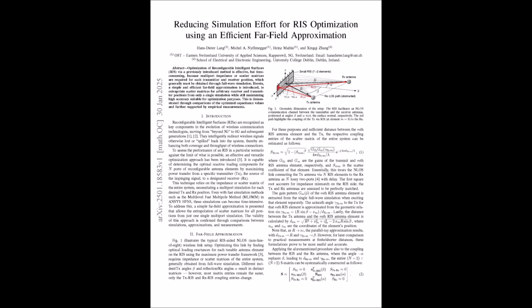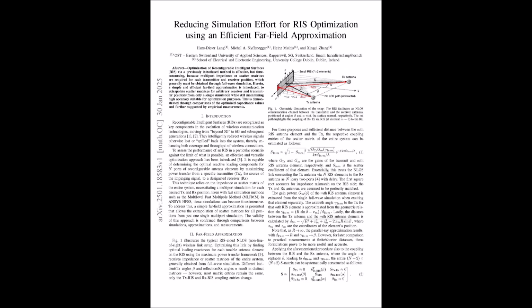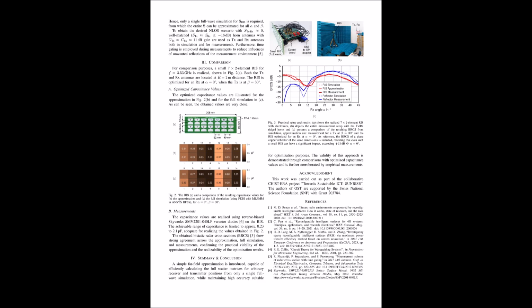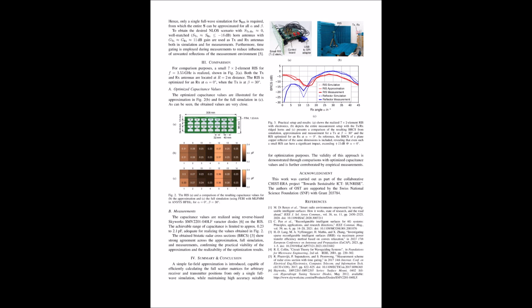All right, so we've got this big matrix filled with smaller matrices. Can you unpack those submatrices a bit? What do they represent? Certainly. Let's start with S_RIS-TX. That one captures the coupling between the transmitter and each element of the RIS. But it's not just any coupling. It's for a given transmitter angle, which we're calling beta. So we're factoring in the direction of the transmitter now. Exactly. And similarly, we have S_RIS-RX, which captures the coupling between the receiver and each RIS element, but this time for a given receiver angle, alpha.